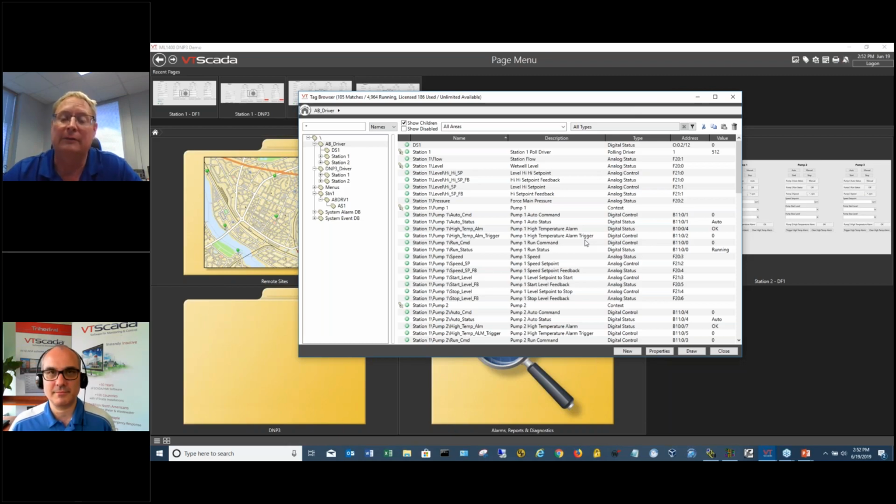Yeah, it's not software limited. It's limited on the hardware side. Like I said, if you had 1 million PLCs connected over a gigabit network, you might be able to talk to all of them, but that would be a pretty busy network, especially if you had a lot of I/O tags. And if you're pulling them every second, or every 1/10 of a second, then you're going to overload your network again. Again, the software is not limited. It's the hardware that's the problem in that sort of scenario.